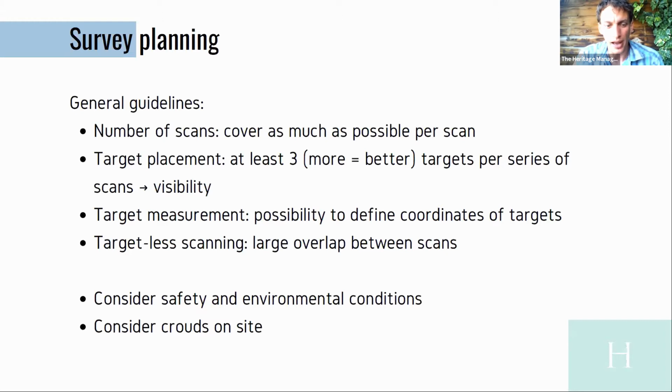In general, I must say that people are very interested in topography, and in a laser scanner they see something rotating with a lot of lights and making a lot of noise. So people are interested in it. They will look at your device, your laser scanner, and the last thing you want to do is, at first, harm these people because they are looking into the laser beam, and secondly, that they destroy your measurement, or even worse, destroy your scanner by touching it or dealing with it in an inappropriate way.